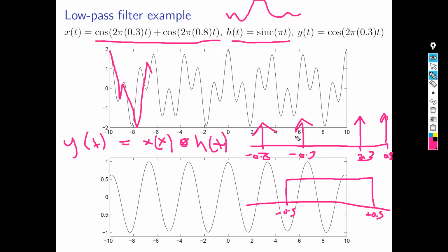Okay? Now, filter it. You have this input signal and you have this system, which is a kind of filter window that allows certain frequencies to pass. Tell me the result. Convolution in the time domain is equal to multiplication in the frequency domain, yes?